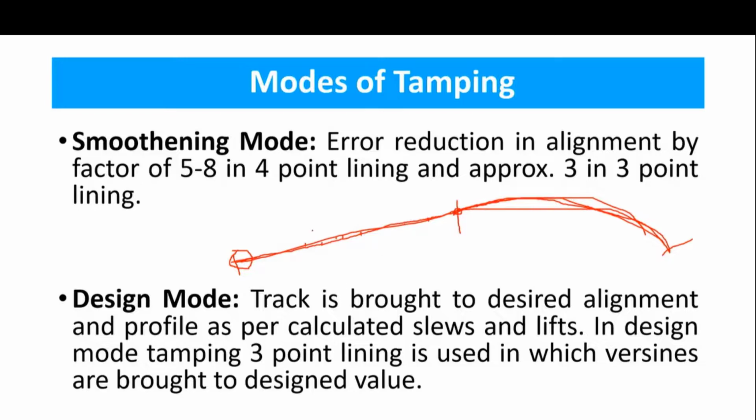And level, of course, we are doing by taking the level at 10-meter interval and then doing the gradient, plotting the gradient profile and working out the lifts.